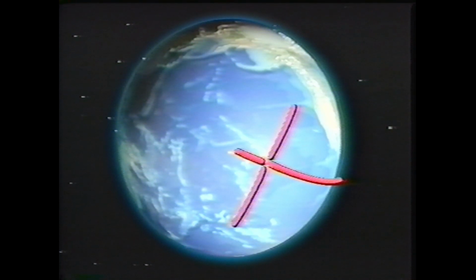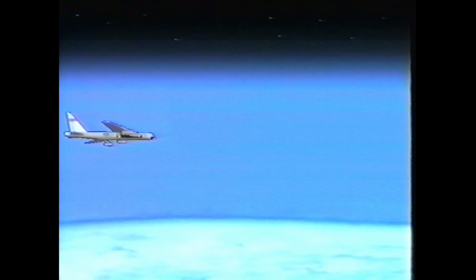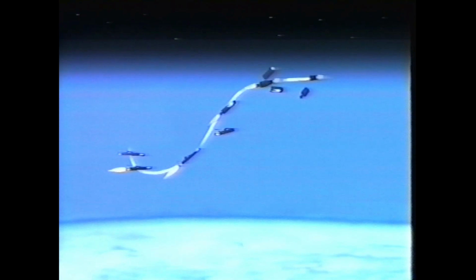Pegasus can launch payloads into orbits of any inclination. Due east from the equator, due north or south for polar orbits, even retrograde orbits. High-altitude suborbital missions can be flown to assist in hypervelocity vehicle development. Pegasus also achieves a breakthrough in launch vehicle performance. Using advanced technology and the air launch method, Pegasus can deliver approximately twice the payload weight of a comparable ground-launched booster. Delivering 900-pound payloads to low Earth orbit, Pegasus fills a gap in America's launch vehicle inventory.